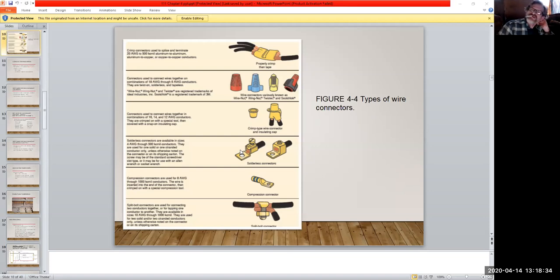They'll use this in weird junction areas. Most commonly, they would do something like this if you had to bring in another additional wire at a later point in time, or you wanted to make a splice where you ran out of length. You are allowed to do this. If you have some good bolt cutters, they usually have a crimp or two on them, which are always nice to have. So you just go through and fasten these down, make sure it crimps, and then, as with any of this stuff, you give it a good tug test, right? If it comes pulling out of your crimps, you know that your tug test has failed.